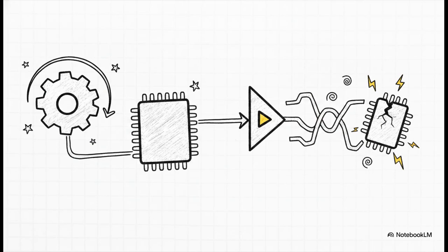To build a sequential circuit, you absolutely must use non-blocking assignments. And conversely, stick strictly to blocking assignments to describe your combinational circuits. Using the wrong syntax here doesn't just give you a tiny software bug. It wires up entirely unexpected, completely incorrect hardware.